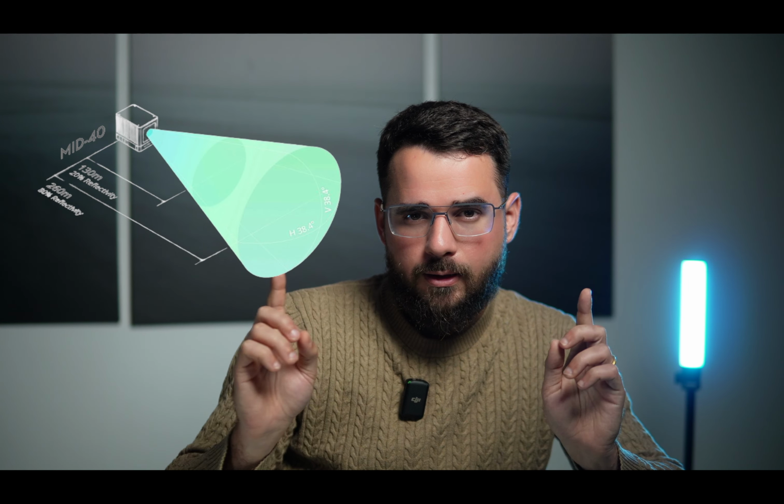Solid-state LiDARs focus on a region, so there is very often a region of interest that they cover frontwards. They don't usually spin; rather, they have some kind of mechanism that focuses on a specific area. It's like you're aiming towards something, which of course is a bit of a disadvantage. So often we want to have as much field of view as possible, as much coverage, as much area as possible. But very often a focused area is really sufficient for a lot of applications.